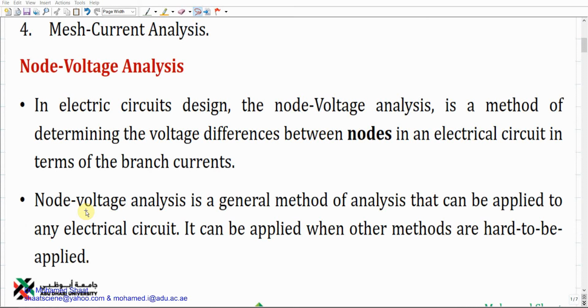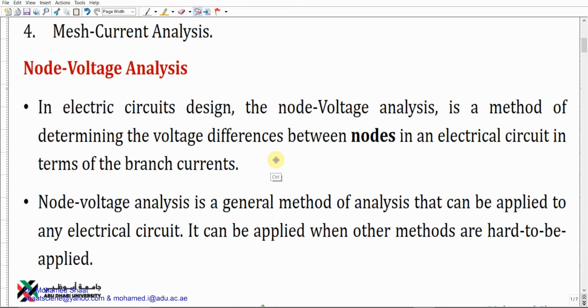There are 2 main pieces of information that are essential to use this method. First, we should have an idea about the voltage over each individual node, and we're going to give a name to the voltage over the node: node voltage. And if we calculate the difference between these node voltages, we're going to end up with an element voltage. So there are 2 terms that we have to distinguish here through this method.